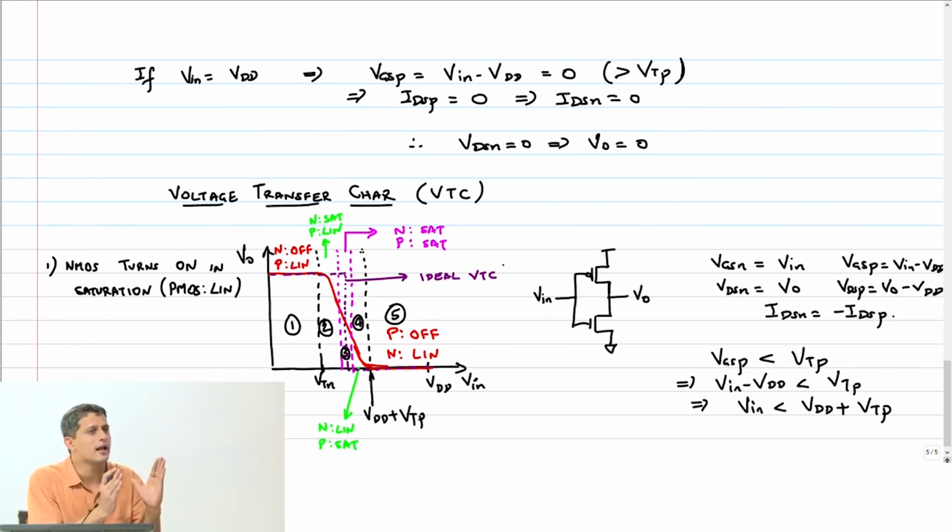Okay, so clearly right here you see that there is a range of input values which are treated as logic low, which means the output will be logic high, right? Similarly, there is a range of input which will be treated as logic high, the output will be logic low, no problem. But there is an indeterminate region in between which is neither logic 0 nor logic high. I'll show you why that happens, and this is of primary importance to us because this is where the input should not land.